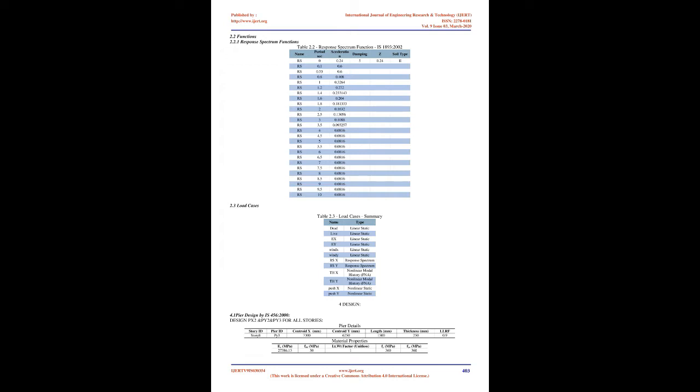Aniket Akale, 2017. Carried out the wind and seismic analysis of 15, 30 and 45-storied buildings of 4 different shapes of same area by using advanced software CSI ETABS. Response spectrum method was used to find the dynamic effects. The comparison has been done by considering the parameters such as story displacement, story drift, base shear, overturning moments Mz, acceleration and time period.